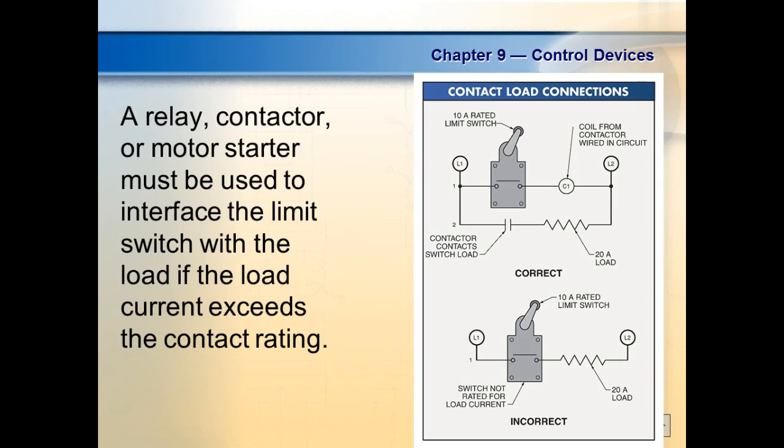But the inputs on those things are like 20 milliamps. So you'll look at some of the limit switches we use on PLCs. They don't have to be nothing. But the PLC, we could bring it into the PLC, the PLC output could bring in a big contact, right? You understand? Most PLCs could run a 2 amp load, which would be a really good sized relay.